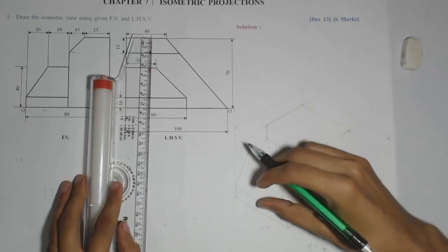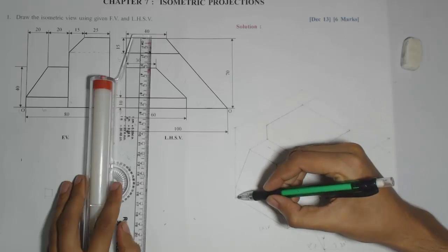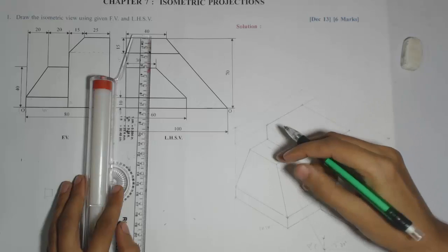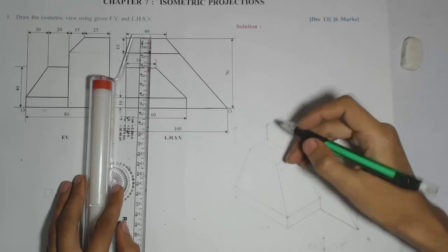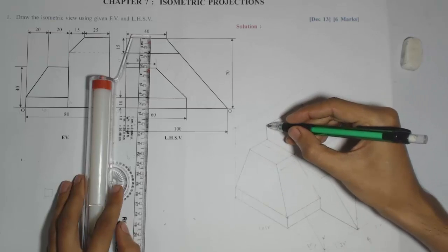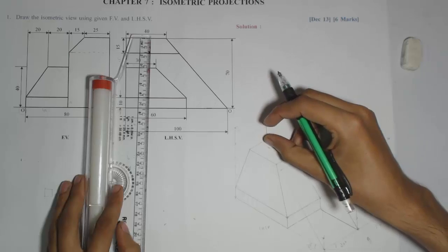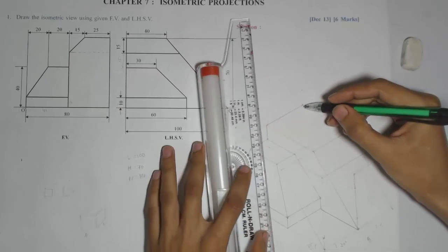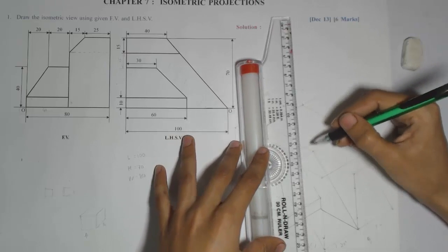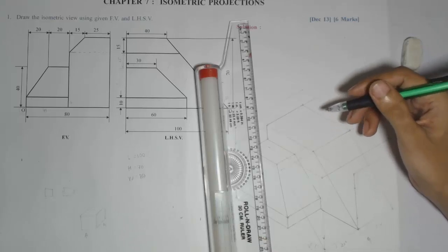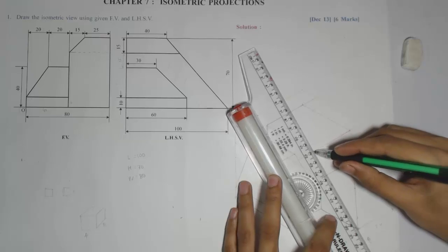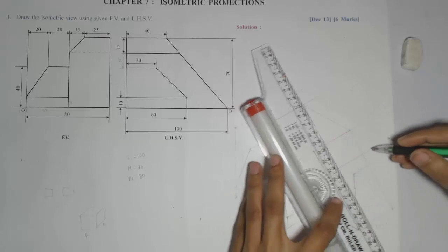Actually, if you see the view drawn on the left hand side, it is going up to the bottom, but if I produce this line up to the bottom, that will not be visible because this part is coming in front, so that line is not visible. So we need not draw that up to the bottom. We should draw up to here only because only that part is visible. Similarly, if I draw the same line from this corner, obviously that is not visible to the observer, so we need not draw that. So now the view which we have got is these two lines for the actual object.